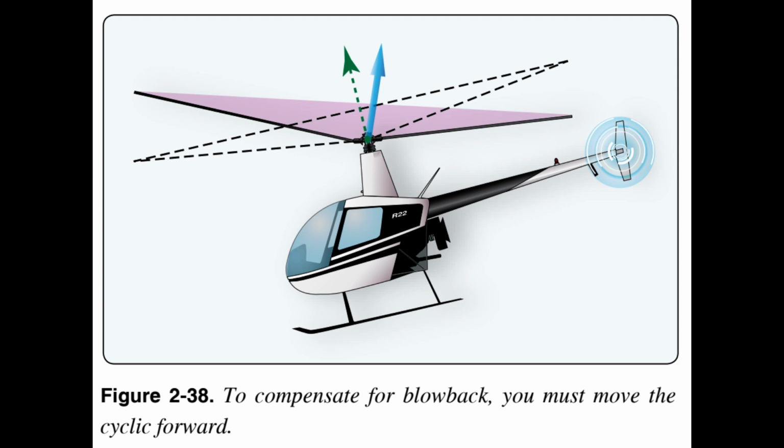A horizontal lift component, thrust, generates higher helicopter airspeed. The higher airspeed induces blade flapping to maintain symmetry of lift. The combination of flapping and cyclic feathering maintains symmetry of lift and desired attitude on the rotor disc in the helicopter.